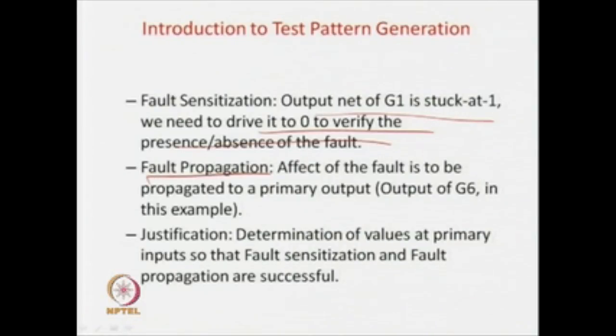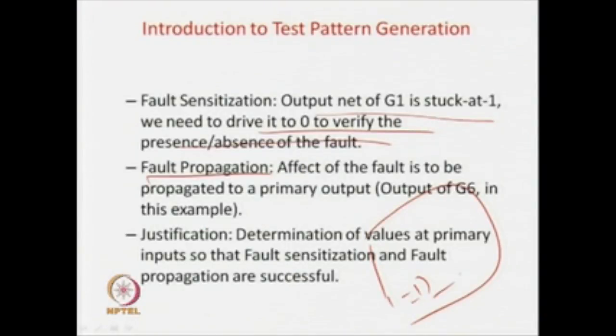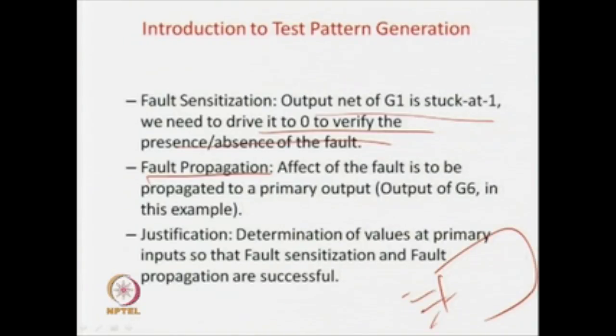As already discussed in the last lecture, for structural testing with fault models, you do not need to bring out any extra pins, nor do you require any multiplexer arrangement, nor a shift register kind of thing. If you have a circuit with a lot of gates inside, with primary inputs and primary outputs, we do not require any extra pin outs or shift register to control these. So, in structural testing with a fault model, whatever you have to do, you do it from the primary inputs and the primary outputs.